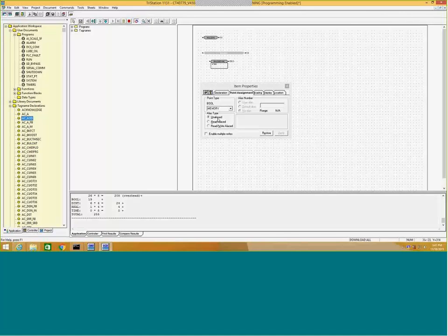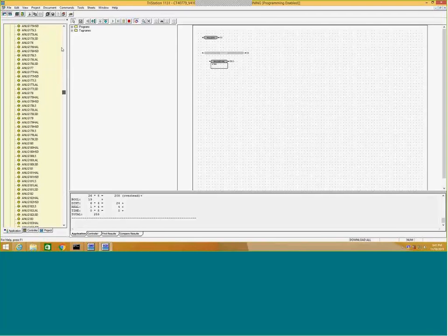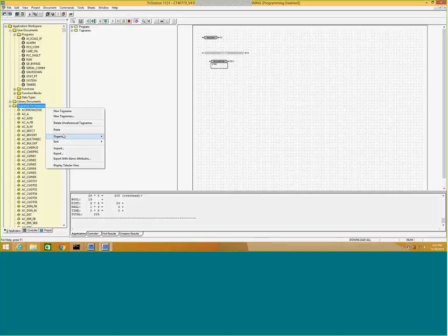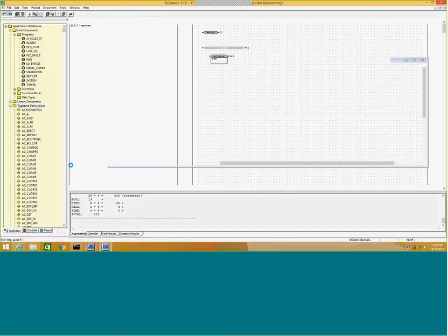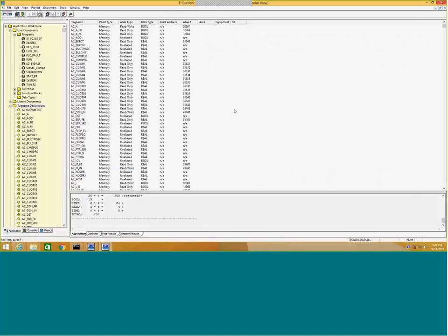this is an alias, or I could enable read alias, or I would change and put another alias. So let me open here a window where you can see a tabular view of all the variables. There you go. So if I scroll down here, I see that some of the variables are read-only, others are read and write, because some start with 30,000, others start with 40,000.